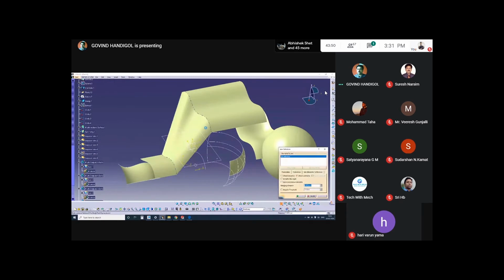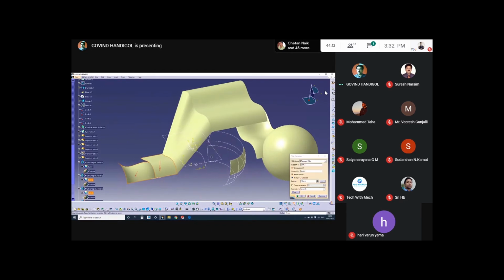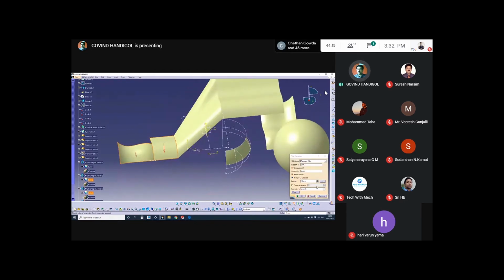And before that, if you want to give fillets, suppose I want to join these two. Now it is joined. Edge fillet option. These are the shape fillets. Shape fillet means between two surfaces. You have to keep the direction, give the fillet here. Give a 15 mm fillet. Here it is going to form the tendency. Let us see. Okay.